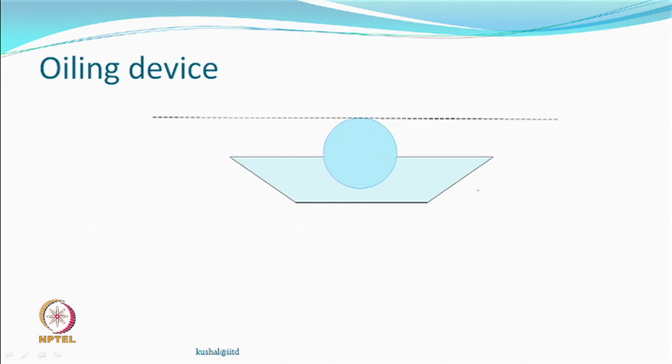So, every machine will have a drawing zone, which may be used, may not be used. The oiling device is needed only in case you have used a heater, because the POY may be spin finished with the same type of spin finish as is being used for false twist. It may have components which can get evaporated, then you would require an oiling device.